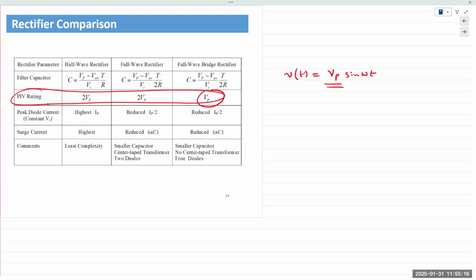The power supply board sends different levels of voltages everywhere, but one thick cable goes directly onto the side of the tube. It's a few thousand volts inside your television. That's why they always said, do not open it up. It's to accelerate the beam that goes on the tube because it's scanning.